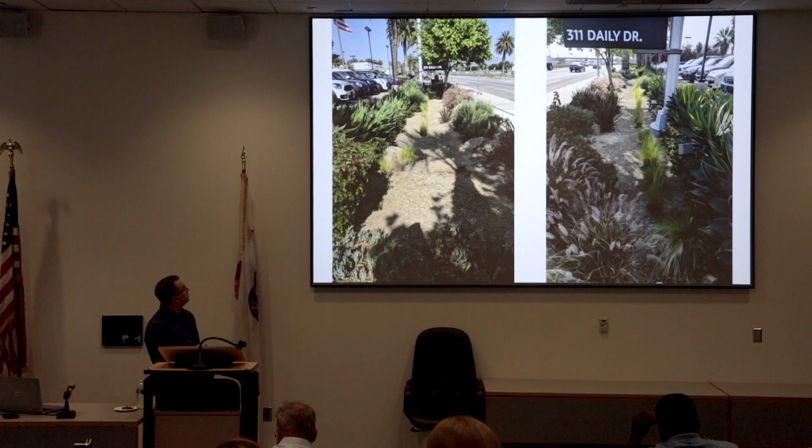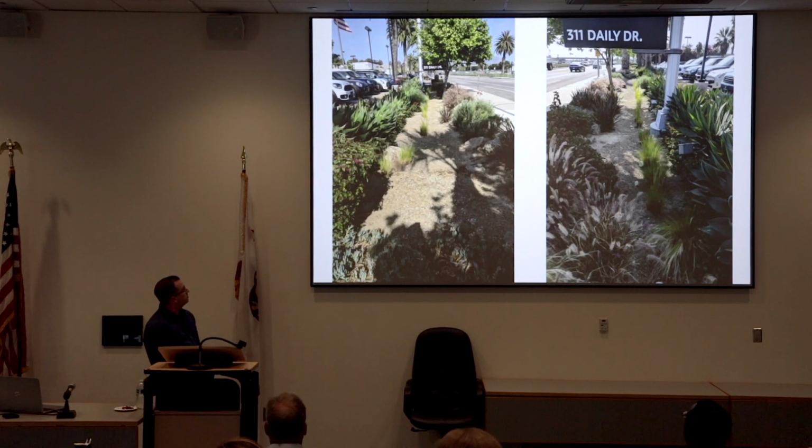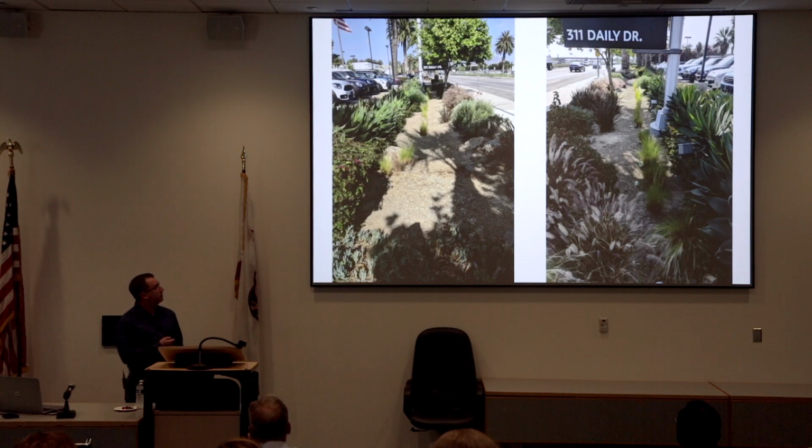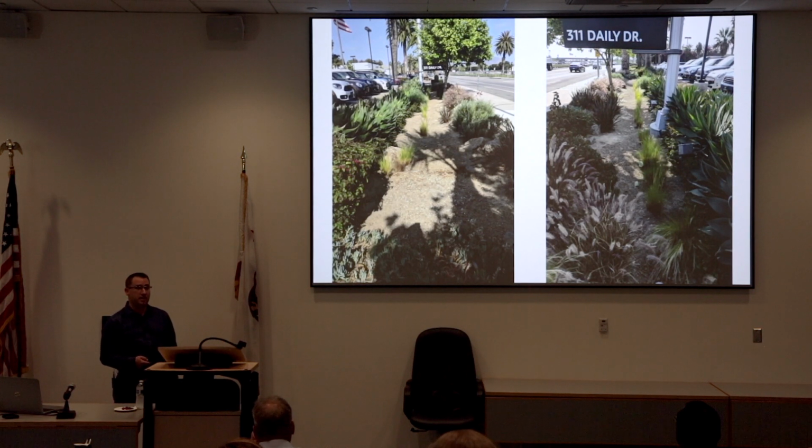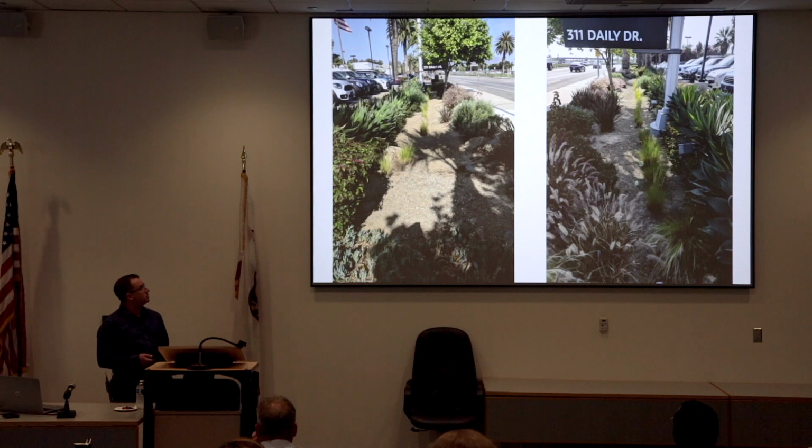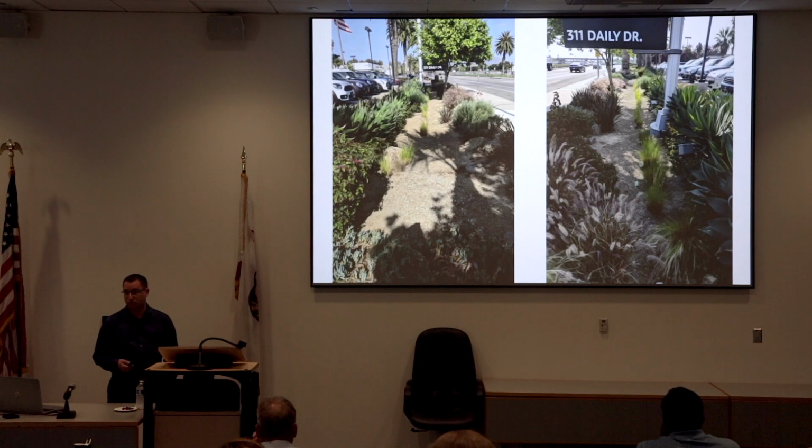So this is what it looks like. It captures the water from the parking lot you can see right here, and it lets it run through all of this vegetation into this area, and then eventually it goes down into the perforated pipe that's in there, gathers it, and lets it flow into that infiltration basin. So it's a neat little design. It actually is flourishing. It's working well, and it looks nice. I know we have a maintenance and access agreement on this where they're required to maintain it, and they're doing a really good job maintaining this one. You can't really see on the surface how it's working, but you can see that it looks well maintained.